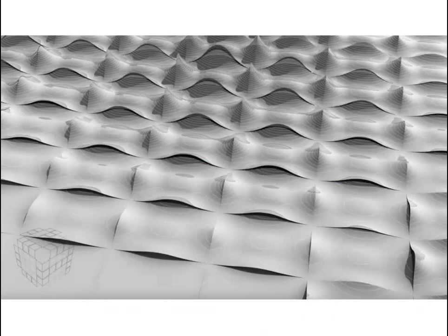And you could get different operations like this surface. So again, this thing's been tiled, but the variance here is actually in these points. There's probably a curve here with a point in the center, a curve here with a point, and the z-coordinate of that point is changing parametrically, and when that curve is redrawn, you get that kind of bulge, almost like a fish gill opening up. And we'll talk about these later in a future class. But basically, you take those curves and that makes a surface.